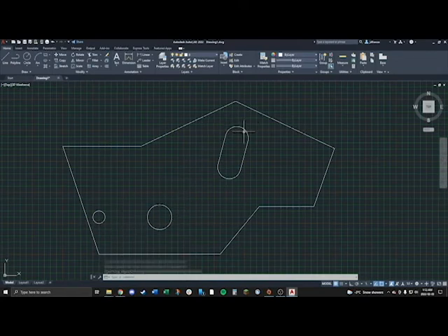So now the most important part is we want to double check every single part of this drawing. So I'm going to start off with ID point. So I know the point needed here, we want it to be 80-80. I'm locked on and I can see that it is 80-80. Here, if you just click the outside of the circle, you'll get, this is 30-80. That's that, and that's that. So these numbers really don't mean anything to us now. So we're mostly checking any given points. So that's 80-50, that's exactly what we're supposed to have.